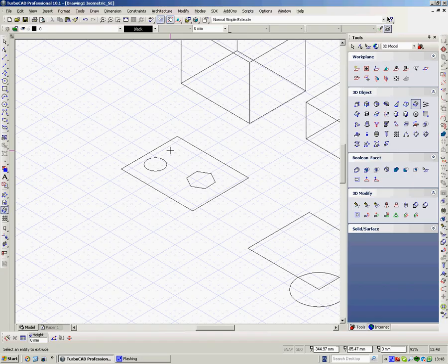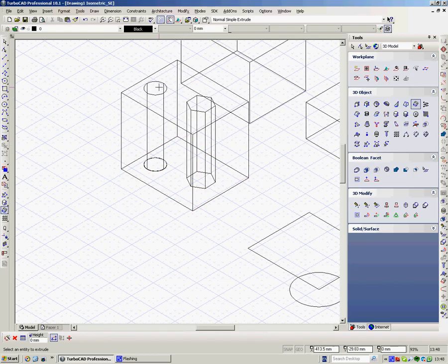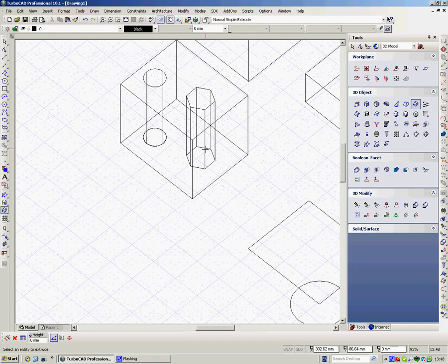Now if this is not turned on, if it's not highlighted, and I extrude these three shapes, this rectangle, this circle, and this prism shape, we will have three solid shapes: two solid shapes within an outer solid shape. If I click that on, it will presume these shapes within the outside shape are holes, not solid objects. So I've got it on, put my finger on shift, click onto there, there, and there, take my finger off shift, that's extruded them, and these two things here are holes, they're not solid objects.